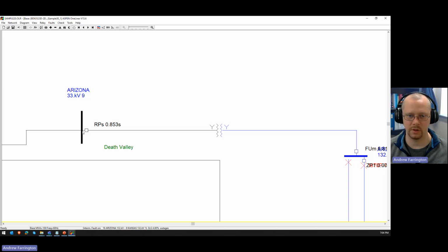And then three-phase customers may have poor power quality, to say the least. So you want to avoid that if you can. The recloser is probably a three-phase device, so all three phases would open and you're going to have that customer power quality problem. But I should have also said that fuses don't reclose.